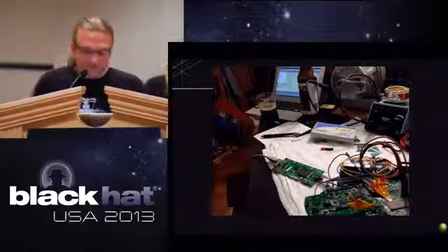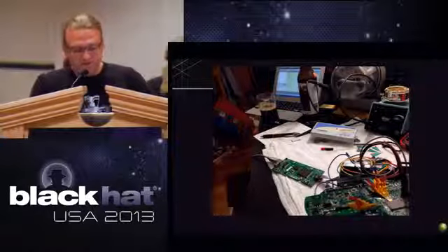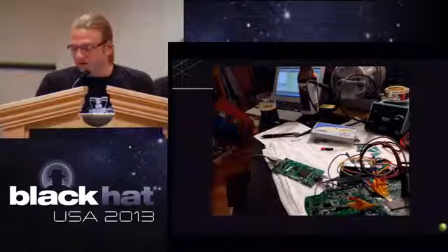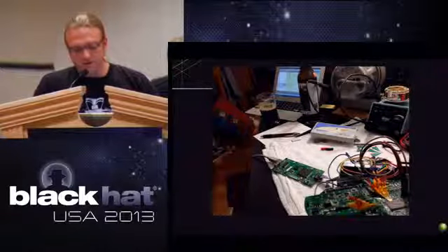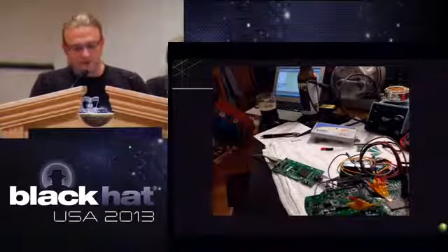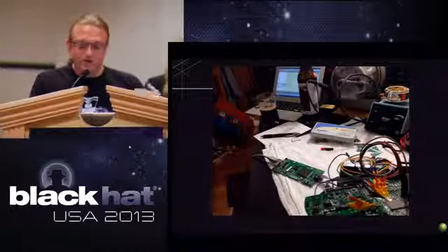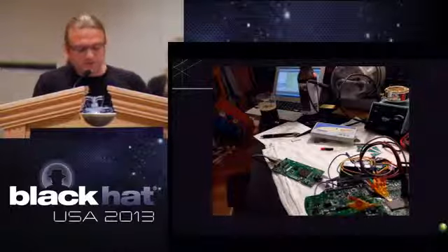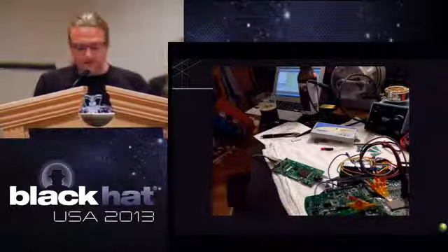That's true. The chip doesn't. The board does. But you can see, like halfway back, we've actually got the vendor supplied debug port. So I'm able to control debug. But as I'm doing that at a software layer, those little micro grippers are letting us do a full logic analysis on what's going on the wires. So we're able to track more things than the vendors let us get to, and start digging a little deeper.